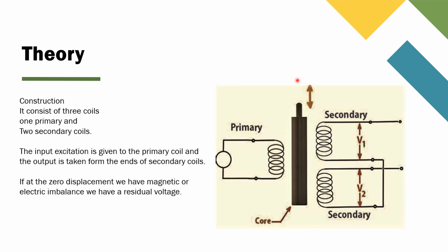And if there is some electrical or magnetic imbalance, then even when the core is at zero position, we have some residual potential at the output.